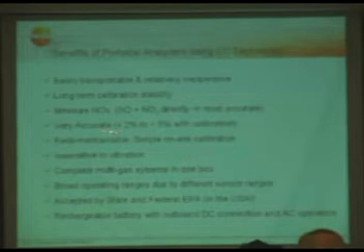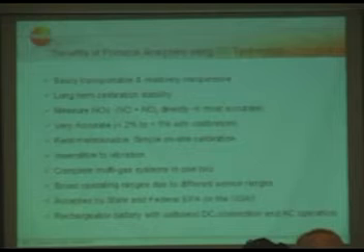The electrochemical sensors are accurate, between less than 2% and less than 5% after calibration. That means even for long-term stability, if you are within less than 5% over 1 year, that's a very stable reading. One advantage is they are field maintainable.